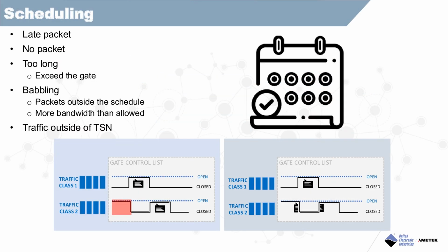Okay, so let's assume synchronization is working. We can look at scheduling next. One question to be answered is, does your endpoint test with a switch or is it direct? A TSN switch also handles many of the error checking and scheduling, so you need to ensure if you're testing your device, you're not testing with a TSN switch that will do some of the hard work instead of your device. Since the schedule is so important in TSN and control systems, proper testing should include modifying or violating that schedule. Try sending an expected packet late or not at all. How does your device handle that?